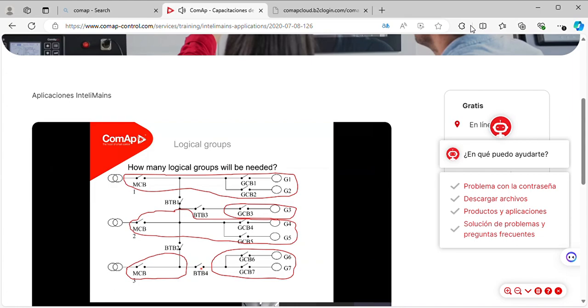So the group linking, or group link left and right, is what you have to key in inside the bus tiebreaker controller set point. If your left is 1, your right will be 2. If your left is 1, again right will be 3. If your left is 3, the right will be 4. So you can cluster them and allow them to link and operate in different sequences. That is very straightforward, to cluster them in different forms.